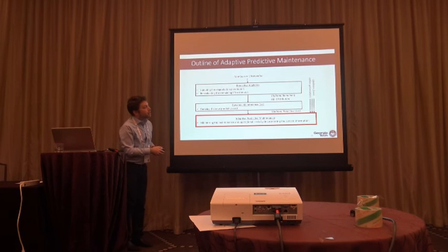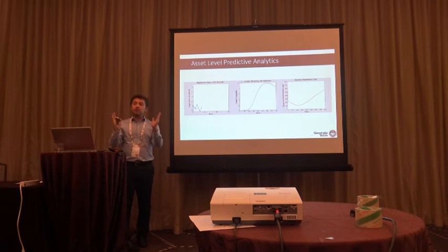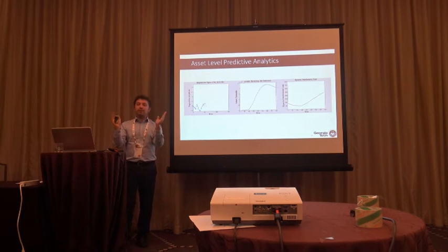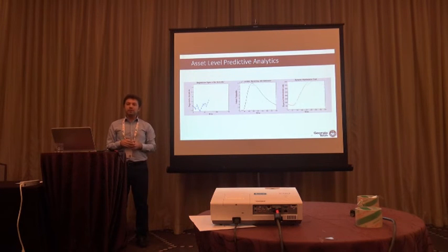So if you are very certain, what happens is that you get a maintenance cost function that's really steep. If you have too much uncertainty, then you're getting a dynamic maintenance cost function that's not as steep, that provides more space for the optimization problem to further investigate whether it can move the maintenance solution from the optimal solution back, postponing or making the maintenance itself a little bit faster. So that uncertainty is reflected onto the remaining life distribution. That is directly reflected onto the maintenance cost function. So it's inherently considered.